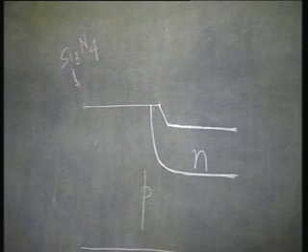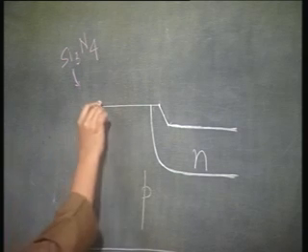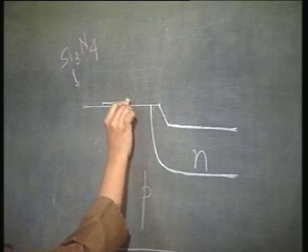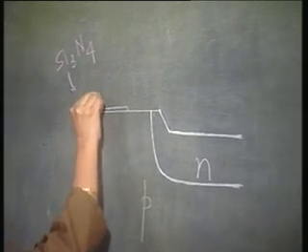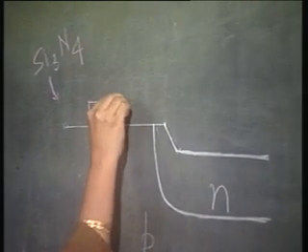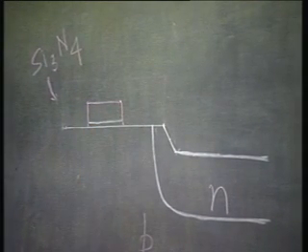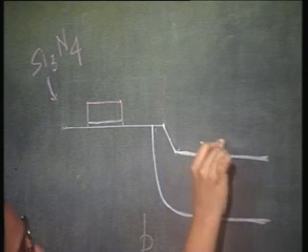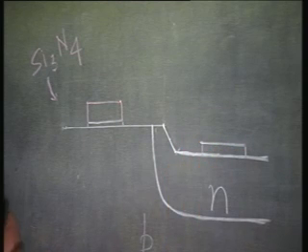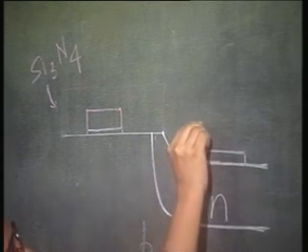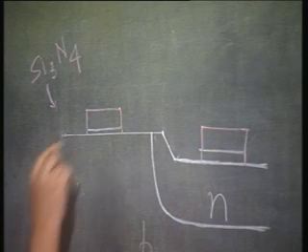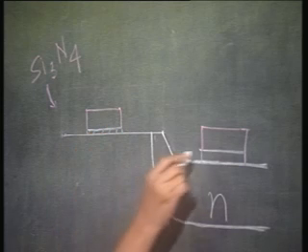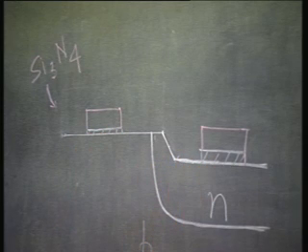Okay. So, again you see you have to carry out oxide nitride combination and pattern it. And then carry out LOCOS.